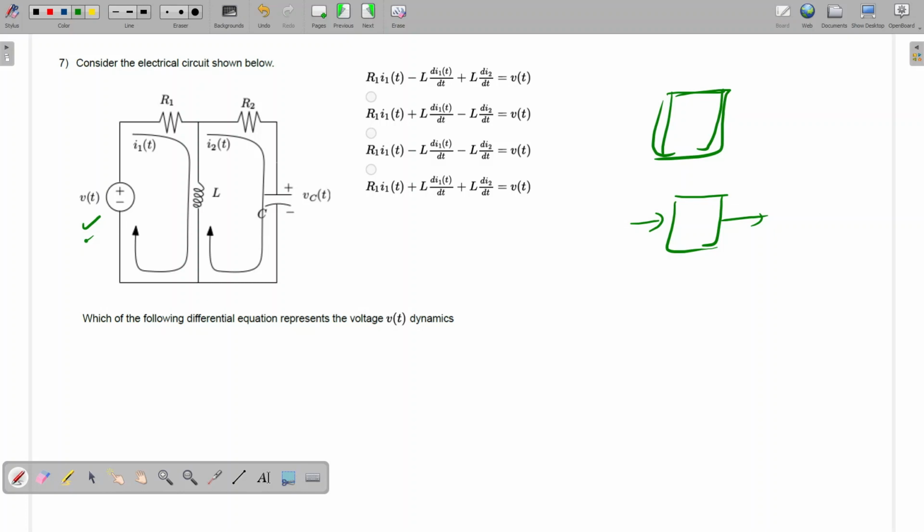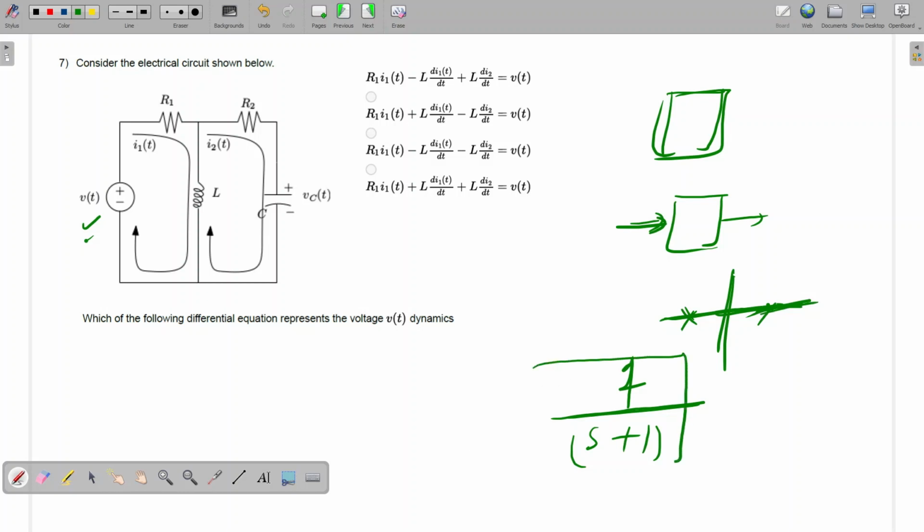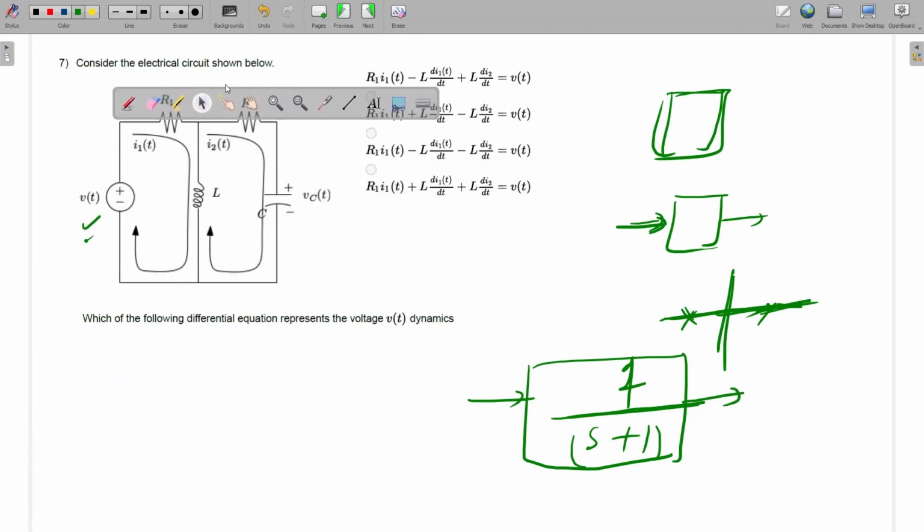Okay. See, he has told that the pole should not be in the right half plane. This is pole 0. This is the right half and this is the left half. A transfer function, let's say, 1 by s plus 1. This is one transfer function. Where is this pole? This is in the left half of the S plane. Some input we are providing, some output we are getting. Let's say I'm providing a step input. All of you know Laplace transform?